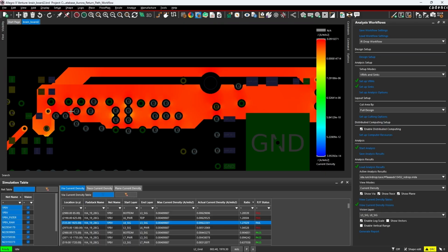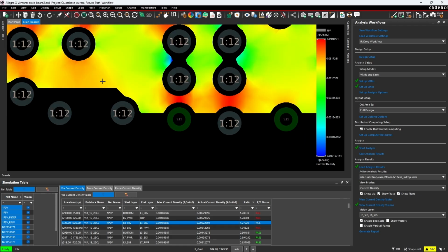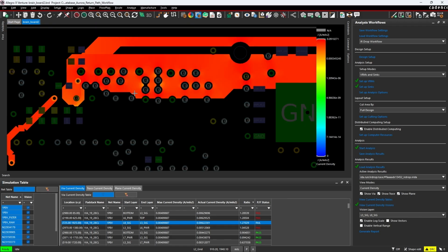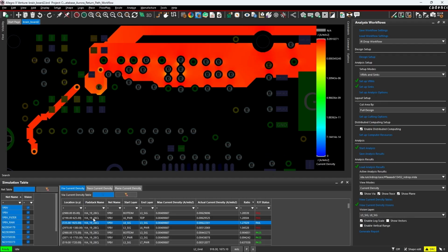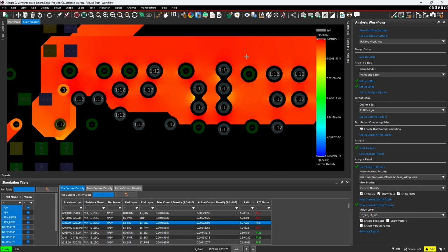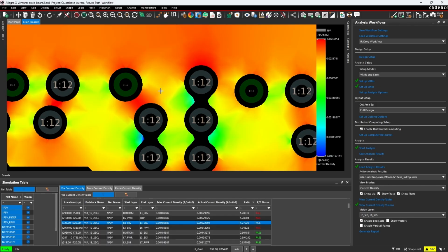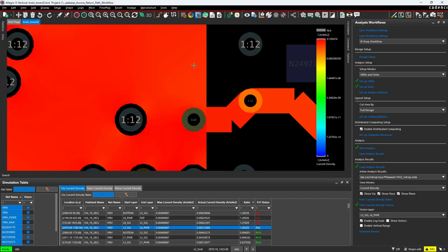You may want to add more vias as needed, even on the plane. You may actually want to add more grounding vias as well to more efficiently get energy through the dielectric and distribute those currents and the electrons appropriately. Yeah, these areas right here are forcing the electrons through narrow areas. They're forcing the electrons through them, and that becomes a problem. Little bottlenecks here. Also happens, let's say you have many vias but insufficient power planes.